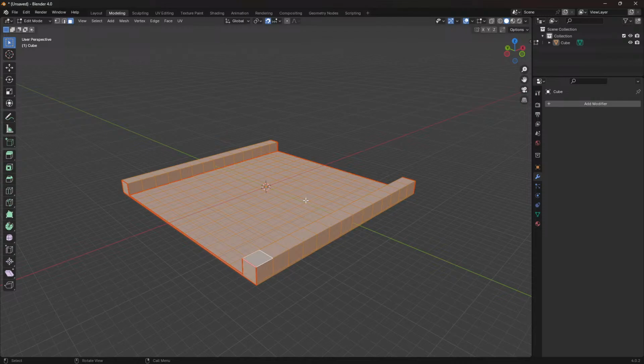And if you curve that spline to where it has like a curve in a road where the road curves, and let's say this was a road, what would end up happening is it wouldn't be able to bend the model correctly. So by having these extra edges in here, this whole entire model will be able to flex and bend. So it'll be able to go up and over hills and things like that. It's really going to add some really cool stuff.